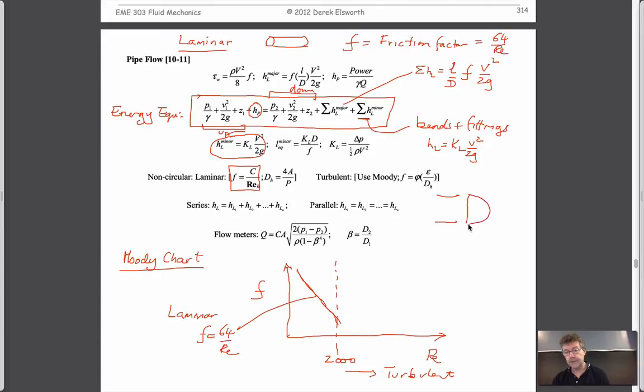So in other words, as a consequence of viscosity, the velocity on the edge of the pipe is anchored at zero velocity. If you go next to it, it goes a bit faster. Goes next to that, it's a bit faster, until it's fastest in the middle, and then it recedes off to the back. So that's the simplest way. Laminar comes from that terminology. What we don't know is what the behaviors are here.